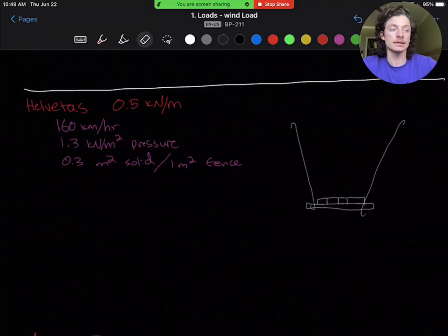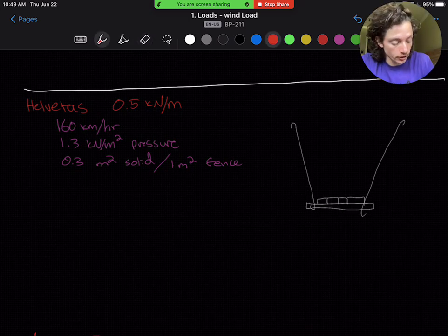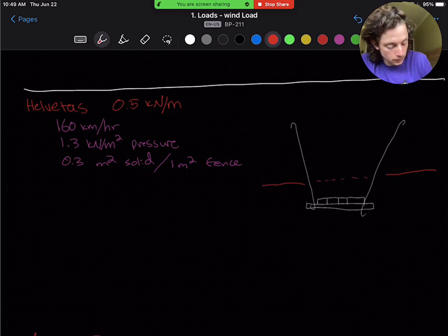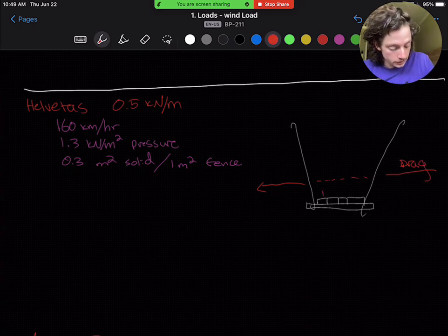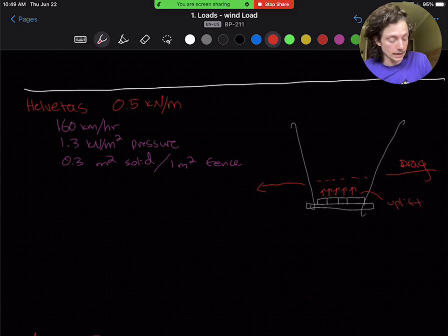Wind is primarily considered along the walkway of the bridge and can cause drag forces or a lateral load, as well as uplift along the deck due to suction and torsion due to an uneven loading of uplift along the deck.